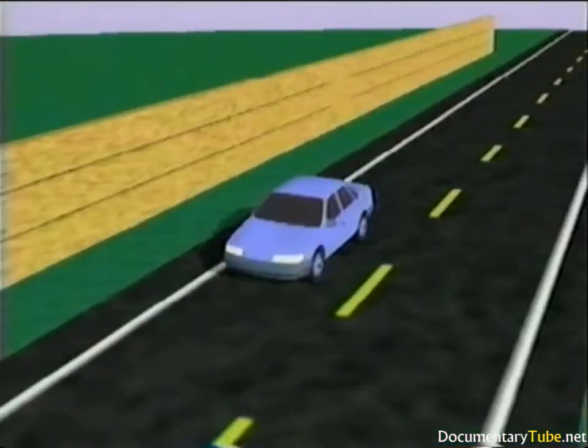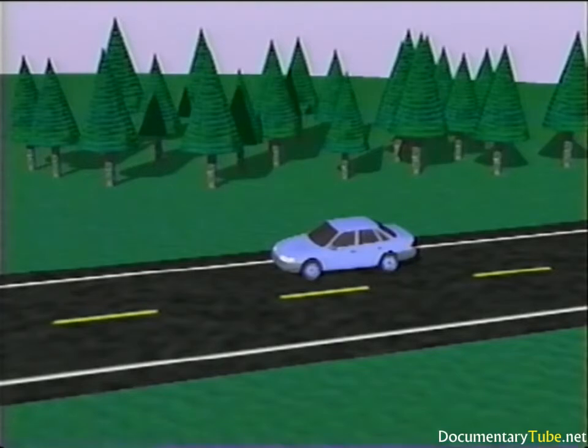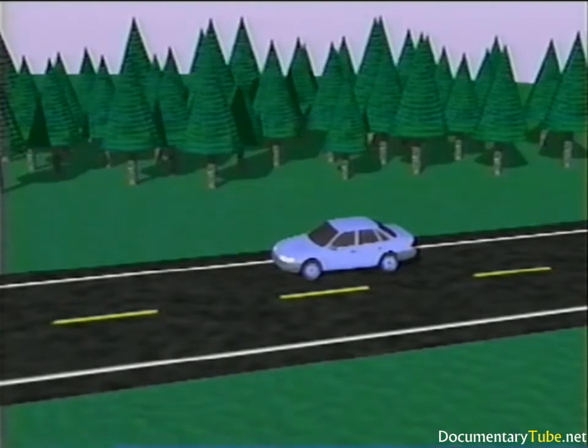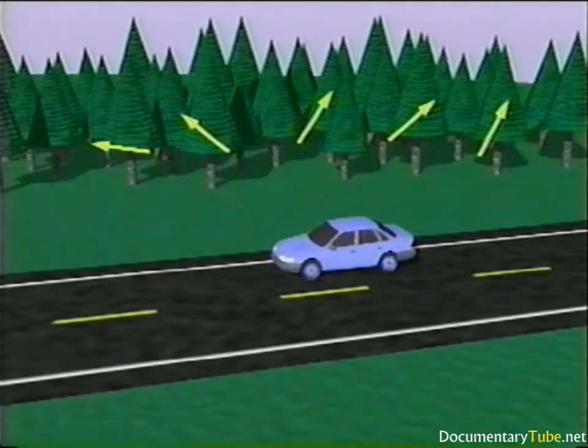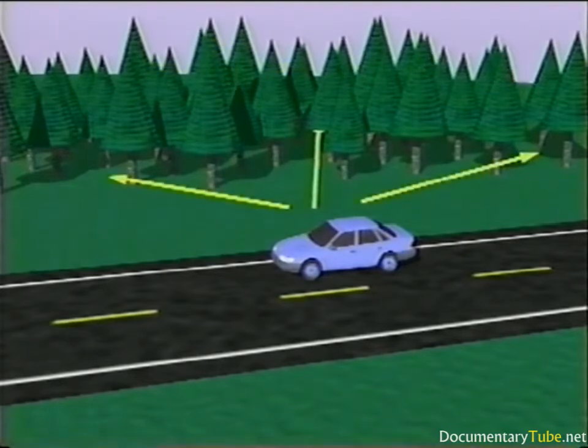In addition to constructed noise barriers and rows of buildings, areas of dense foliage can provide attenuation. Such attenuation is caused by sound scattering into the sky from trunks and limbs, affecting the middle frequencies, and leaves, affecting very high frequencies. Sound absorption by leaves is generally not substantial. In addition, some low-frequency attenuation results from ground attenuation within the wooded area, where the roots of underbrush produce acoustically absorptive soft ground.